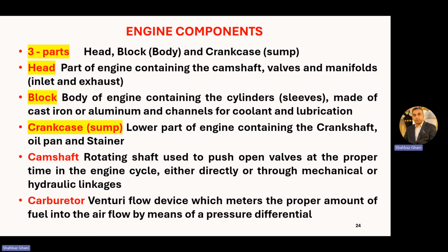The central portion of your engine, the body, contains your cylinders in which we have sleeves in which your pistons move, made of cast iron or aluminum, and channels. There are lubrication channels and coolant channels where the lubrication oil flows and the water or coolant flows. Then the lower portion, the crankcase or the sump: the lower part of the engine containing the crankshaft, oil pan, and strainers.